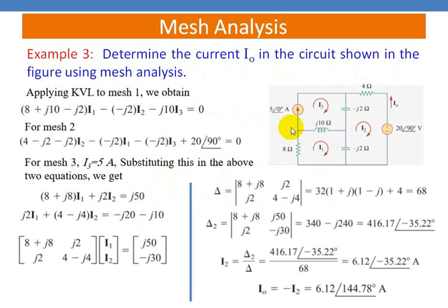So now this is the circuit. Here there is a current source 5 at an angle 0 degree ampere, an inductor, resistance, two capacitors and resistance, and a voltage source. So here there are three meshes. This is one mesh and this is another mesh. This is another mesh. So now you assume currents. I have assumed I1 is the current. Assume the direction as clockwise. You can assign clockwise or anti-clockwise directions, but normally you assume clockwise directions. And I2 is this current, in the second mesh, and the third mesh is this one, I3.